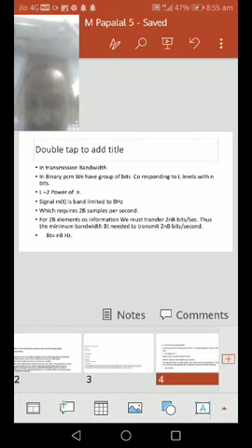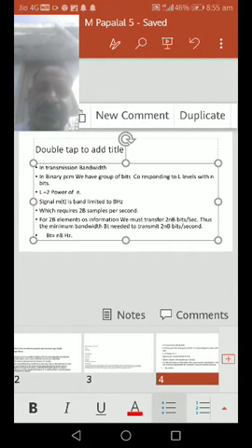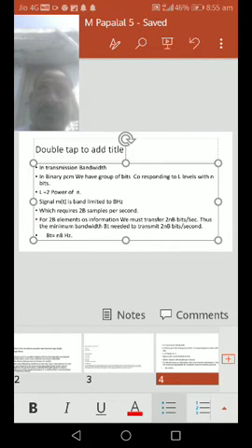The message signal m(t) is band limited to the bandwidth B, which requires 2B samples per second. For 2B elements of information we must transfer 2nB bits per second. Thus the minimum total bandwidth is needed.